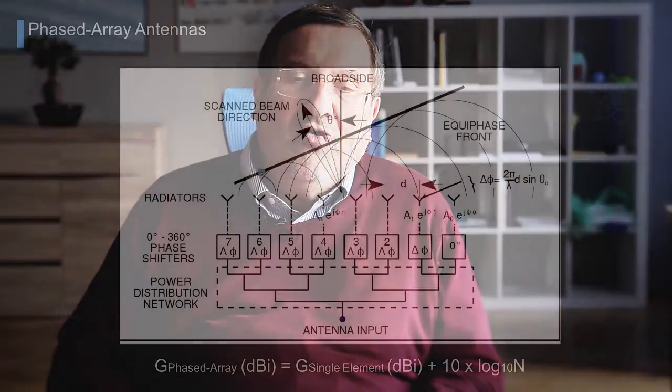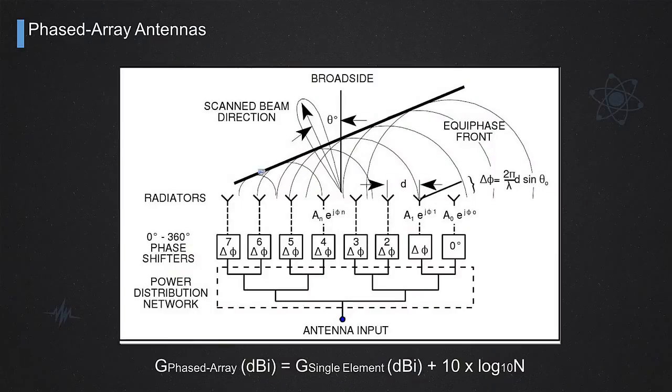In the case of a reflector antenna, we orient the mirror, the parabolic reflector, to get the pattern and the directivity going where we want, for instance, the wanted contour over the Earth. In the case of phased array antenna, we use a different approach. We have an array of individual elements. They can be of different type. They can be an array of waveguide feeds, horns, rectangular or circular, or can be, for instance, patches, microstrip patch antennas. We'll see some examples later.